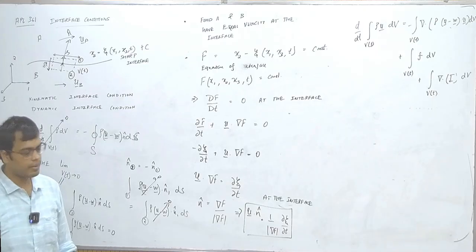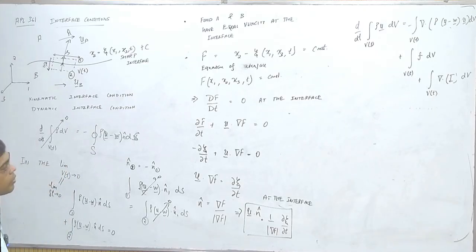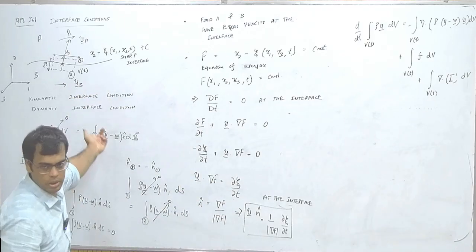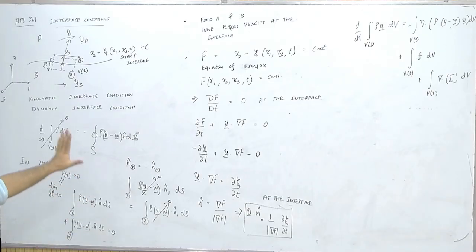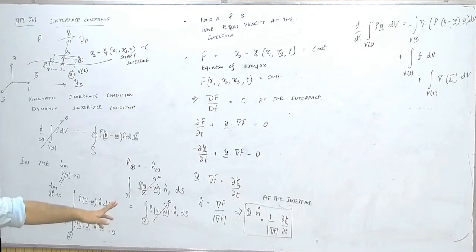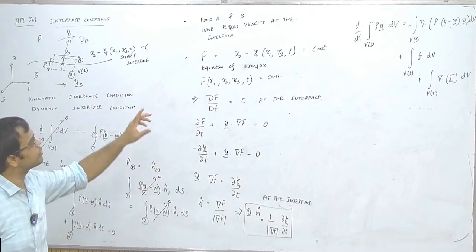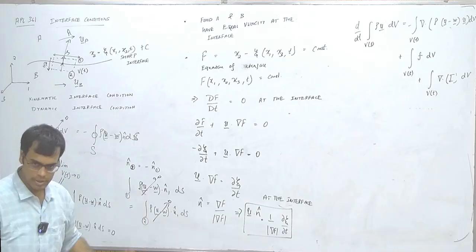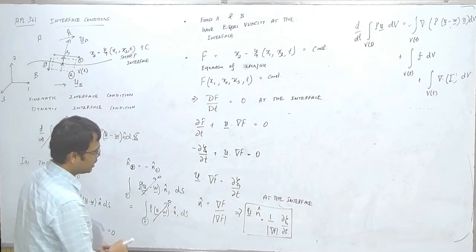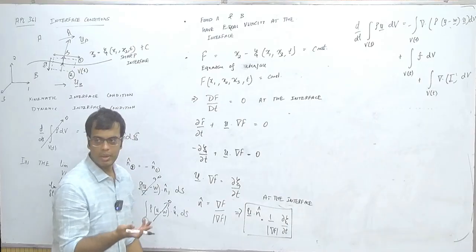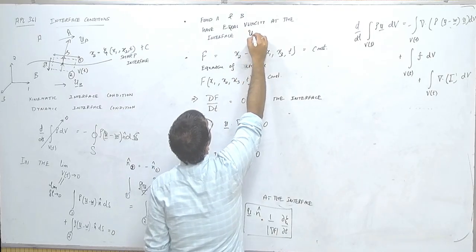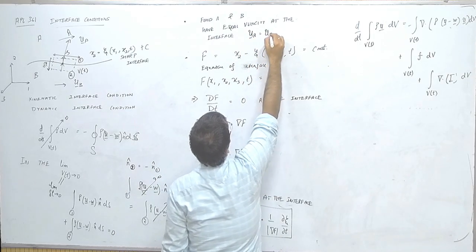So U here represents what? Fluid velocity. On which side? On both sides, one and two. So this can be on A or B, on surface one or two, but there is no control volume here, by the way. This is at the interface. We have said that UA equals UB at the interface, and their normal components are equal to this. This could be either UA or UB, it does not matter since both are equal at the interface. So, maybe let me write this in equation.